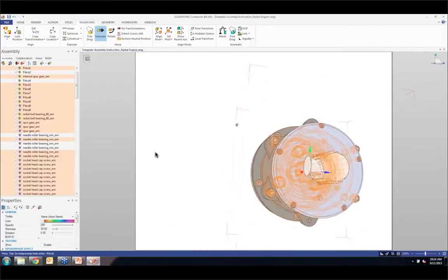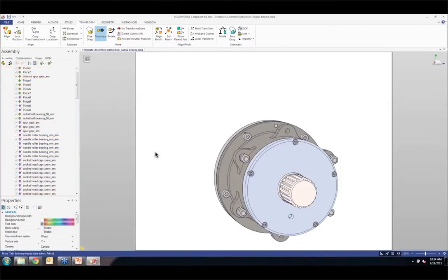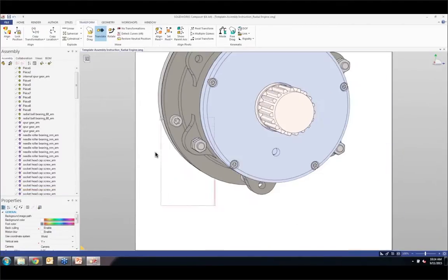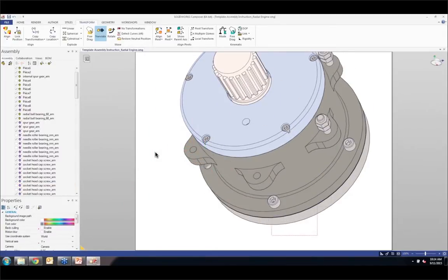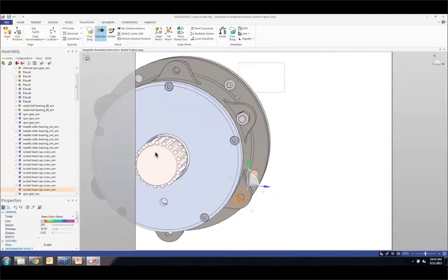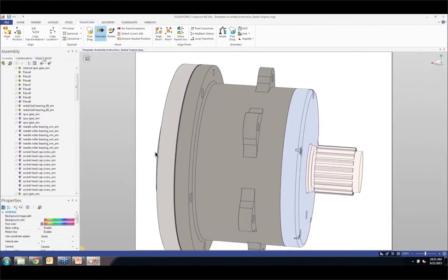And now I say, okay, well, I got a lot of bolts in here that I really don't need for this assembly. So in that case, now I would go from left to right, or right to left, select those guys, and it's just H on your keyboard. It's a shortcut key for hide. And it's an easy way to go through and select these bolts without the fear of selecting something that you don't want to select, because keep in mind you have to put it in that box to actually make that selection, which makes it easier to define that selection. Okay, so something like that, and it looks like now I have exactly what I want.